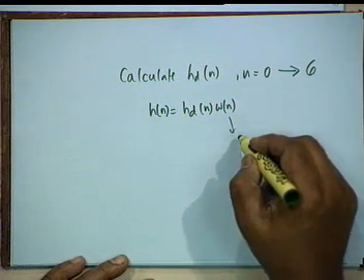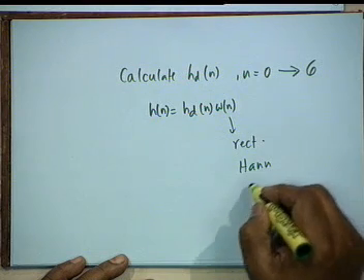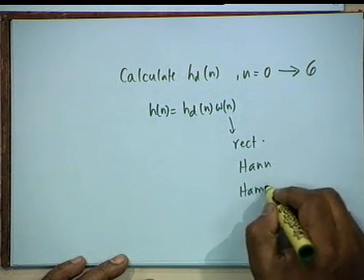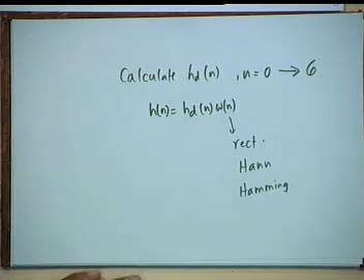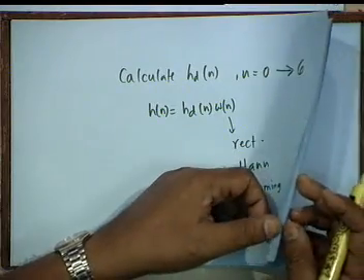we use rectangular, Hann and Hamming. These are the simplest windows that one can use. You have other choices. Even in Hamming, you do not have to assume 0.54, you could assume any alpha. So, there is a lot of flexibility. Okay. And you can calculate the pseudo magnitudes in the 3 cases.